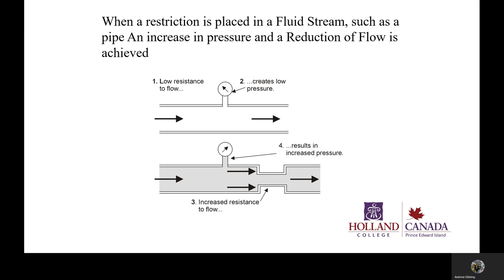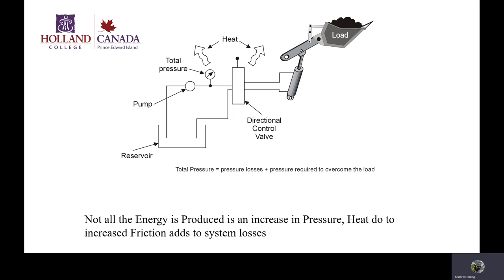So a mistaken belief is that a pump is what creates the pressure. A pump does not. A pump creates flow. Flow, only when it meets restriction, builds pressure. And that's an important concept to remember, because we use that concept all the time to transmit hydraulic power from where it's generated to where it's used. For instance, here we have a schematic representation of a front-end loader.